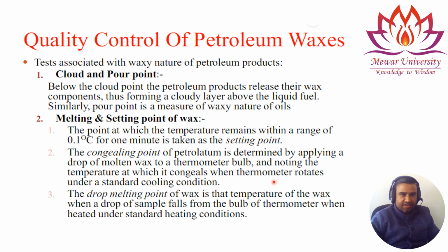Now the quality control of the petroleum waxes. Here we will come to know about the properties of the petroleum that will be tested for the purpose of quality control. You can see the tests associated with the waxy nature of the petroleum product. These properties are cloud point and pour point. Below the cloud point, the petroleum product releases its wax component. Whenever the oil comes to the cloud point, it will release its wax content, thus forming a cloudy layer on the liquid fuel.